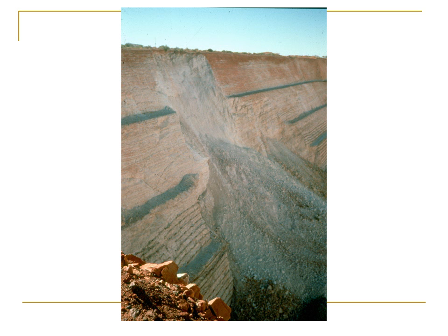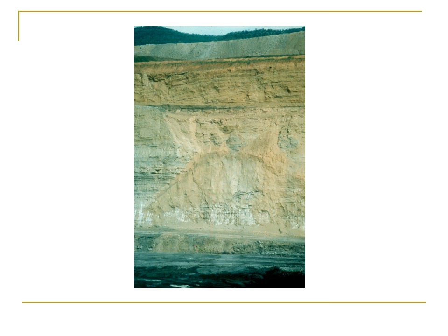Moving down, here's the view of that same slope where you can see the unstable debris in a heap at the toe of the slide, and probably a better view of that rotational failure surface. Here's another. I'm not sure whether this is rock fall or a rotational failure. It's a very steep slope, so it's difficult to say which mode this is. I would probably call it rock fall.